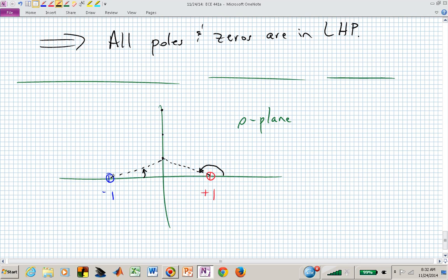And you can then say, oh, I could look at this frequency and I could look at this frequency. No matter what frequency I look at, the magnitude contribution from the left-hand 0 or the right-hand 0 is the same. So you couldn't differentiate these zeros as being in the left half plane or the right half plane based on their magnitude behavior. It's going to look the same.